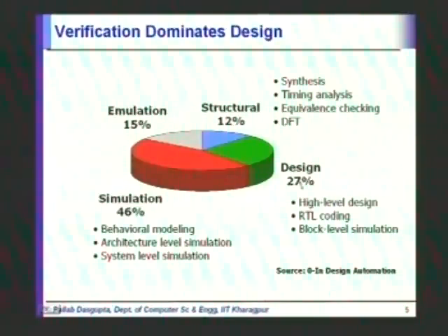And then if you look at the design, the functional design, it takes about 27% of the time, within which again you have this block level simulation, which is also part of the verification. So when you develop individual blocks, then you start simulating those blocks, so that also is taking up your time. Then you look at the structural design part, in which you have the synthesis, and then timing analysis, that's again another part of the verification problem. Equivalence checking, that's also verification, and then DFT.